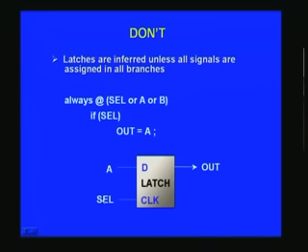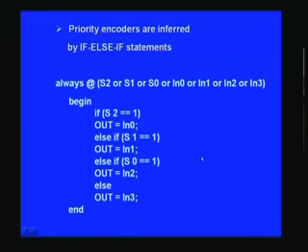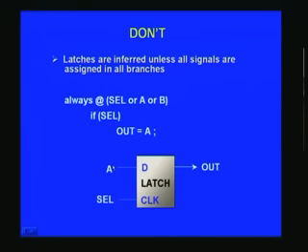That is, when the clock is not applied, whatever is applied to A will appear at the output without any hindrance, and it keeps on changing here. If you have mixed it with a synchronous circuit, it may register at an undecided point. So you should avoid latches here, and the reason for creating a latch is that you have omitted else.